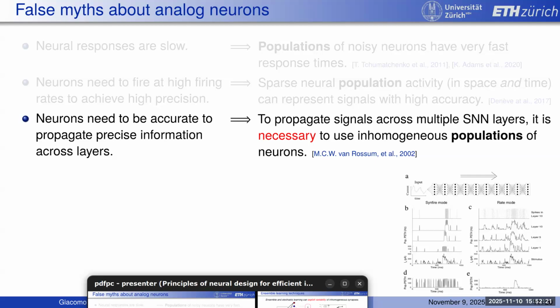Or you could look at the change, and that's true in biology as well. We have transient responses or sustained responses for the neurons. The mechanoreceptors can be looking for static or derivatives. So we can do that also with the circuits by using adaptation or just by sending signals directly into the integrate and fire neuron. But then once you have spikes, this is all in the spiking domain.